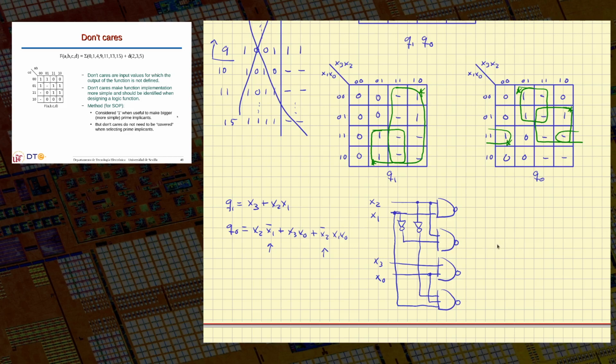Okay, and I have to add all these using another NAND gate. Okay, together with x3. Okay, I have to add x3 to the second level. Now the problem you see that because we are doing NAND, this is x3 alone. Okay, I have to complement x3 to put it in the second level because it's not in a term, so it's skipping the first level and it's skipping the first complement. Okay, as we have already seen.